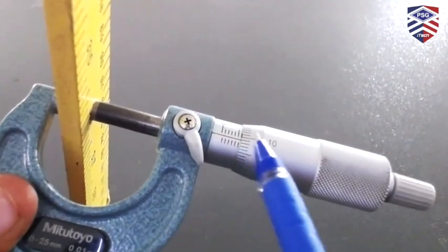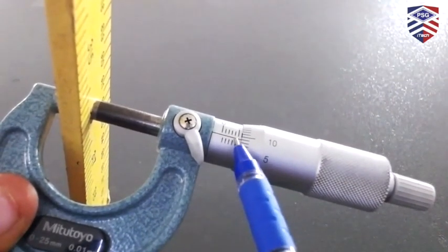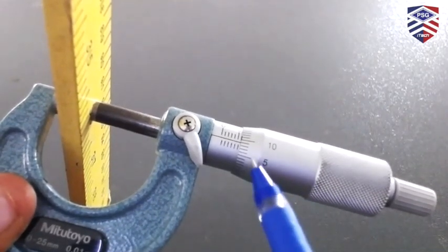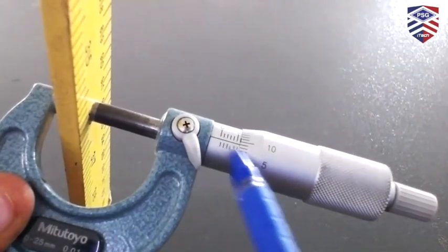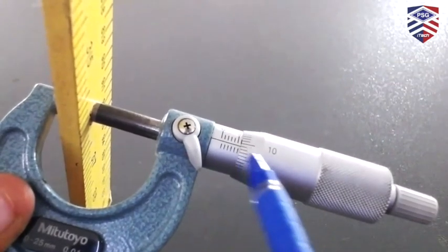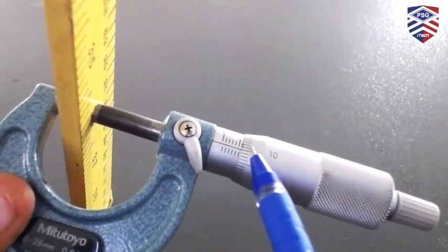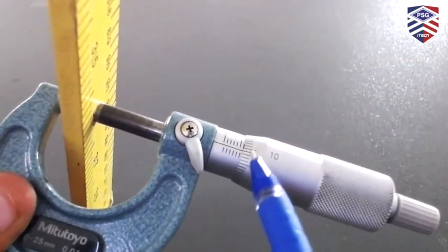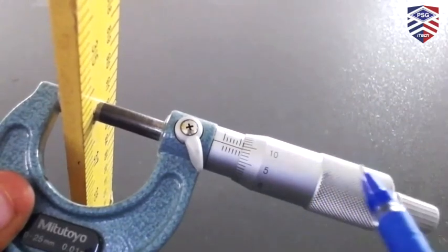Coincidence is nothing but the division on the head scale. Now we can see here is 5, here is 10. So it has crossed 9, and hence the head scale coincidence, the line joining from the pitch scale where it indicates the division on the head scale, is what is called a head scale coincidence. Coincidence, we'll be writing in terms of divisions. So simply write this as 9th division.